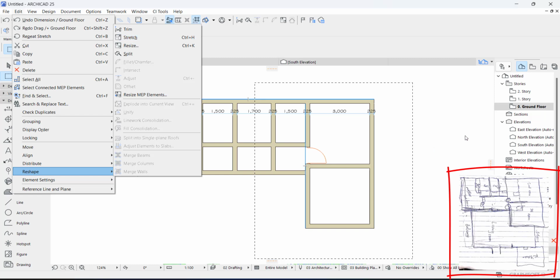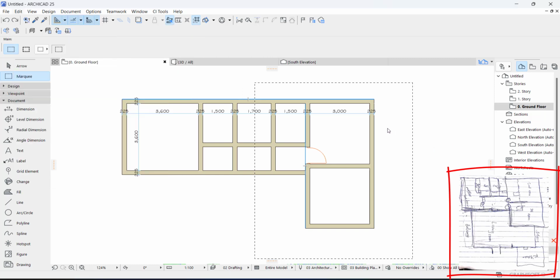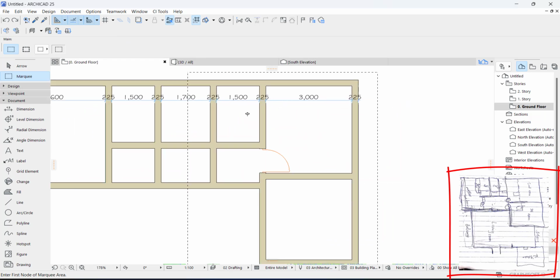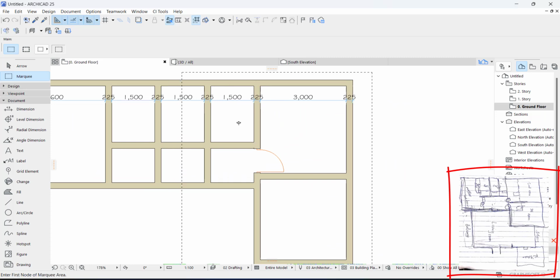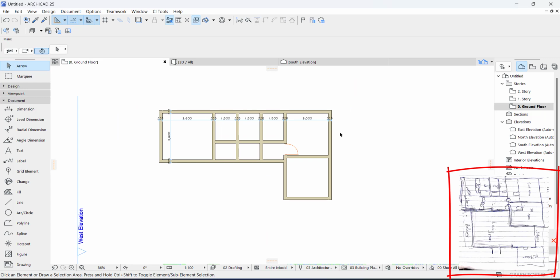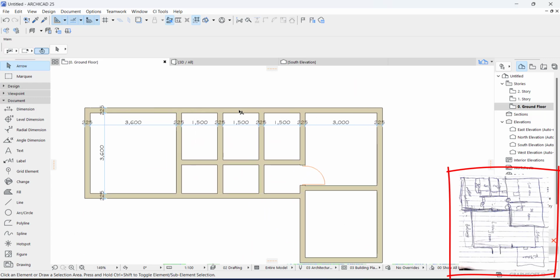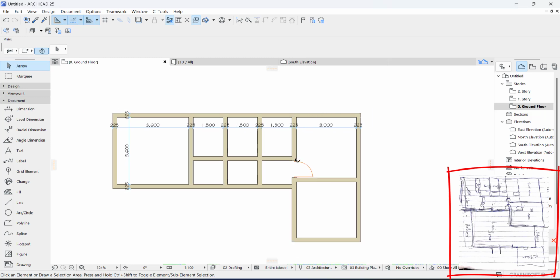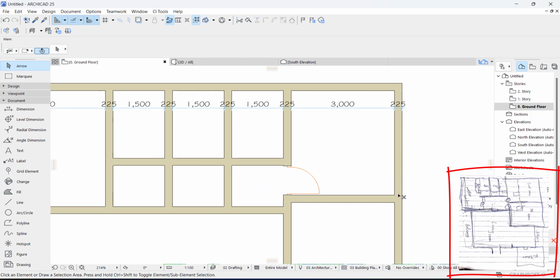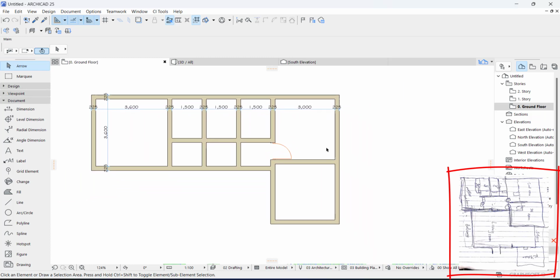Okay, so I'm just going to use Ctrl H now. I want to shrink it a little bit by 200. Then you press Ctrl H, right? Just pick and move. Then you type 200 and press enter. So that's it. We just successfully reduced this by 200 without all those dramas I was trying to do, cutting and all those kind of things. We just did that easily.